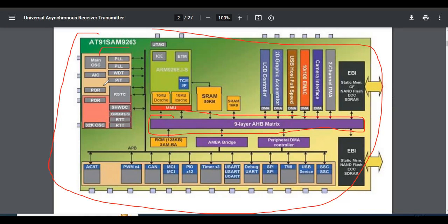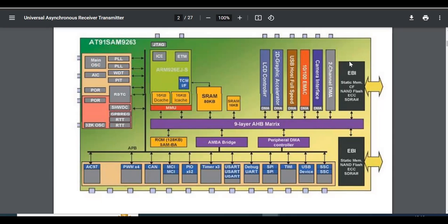Suppose I am communicating from a processor to, say, a UART or a timer. The processor uses high bandwidth, so we need to use a high bandwidth protocol here, which is a parallel communication protocol, nothing but AXI. We have three parallel communication protocols: APB, AHB, AXI. AXI is the parallel communication protocol with high bandwidth, and we need to check the bandwidth accordingly. APB has very low bandwidth, so with APB you need to use low bandwidth components. Like that. Did you get the clarity now, everyone?